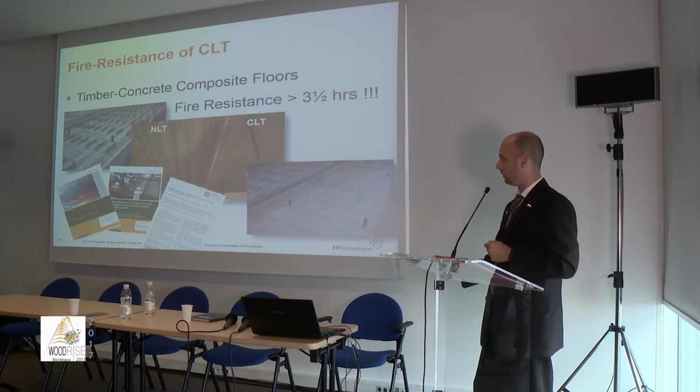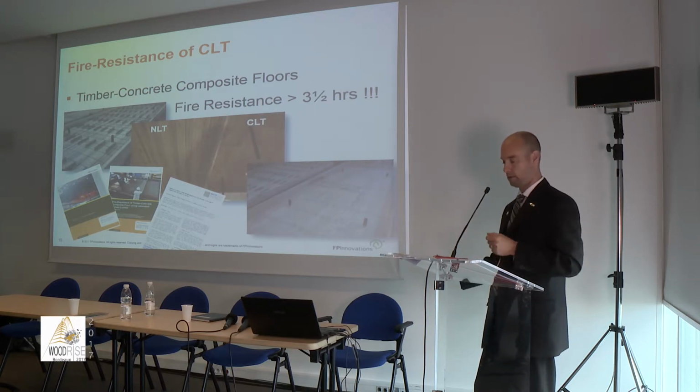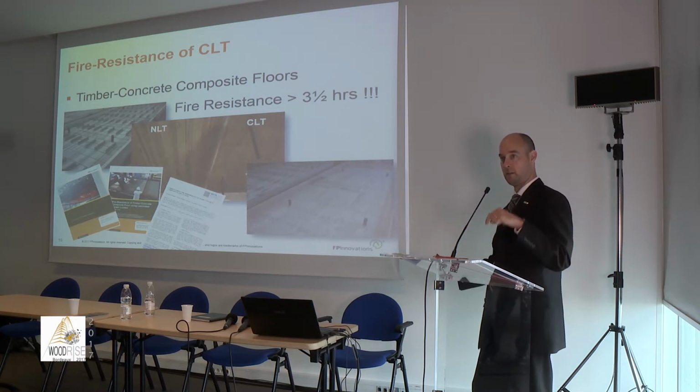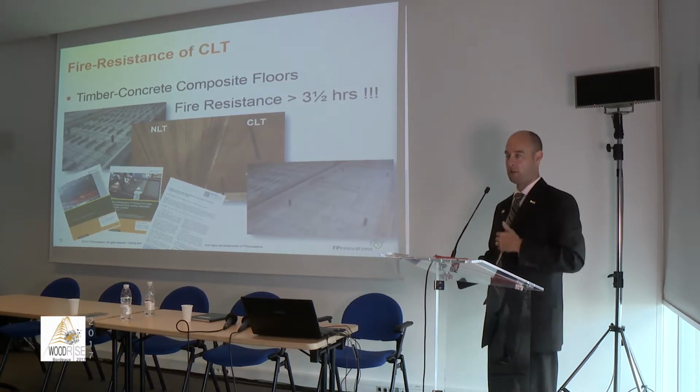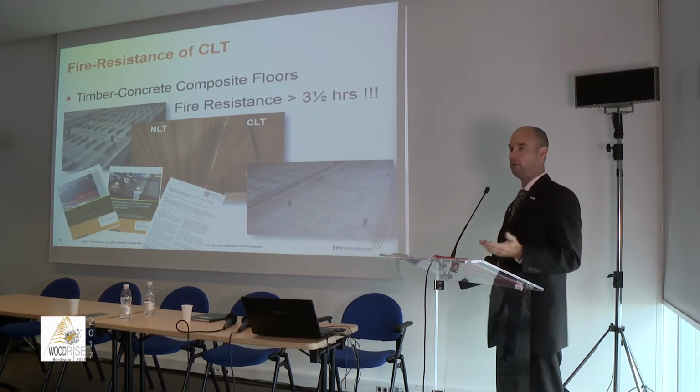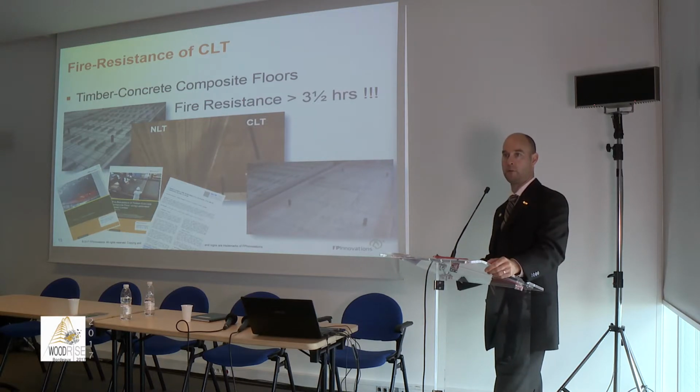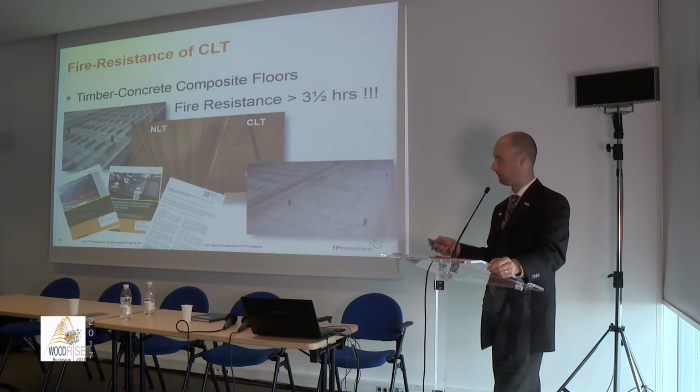And the last one that I'm not showing here was essentially just LVL beams on flat that we drilled bolts into, like screws, I would say, and we just poured the concrete on top of it. And they performed really, really well, well beyond what would be required for a tall mass timber building.